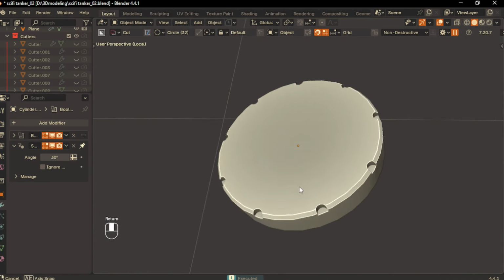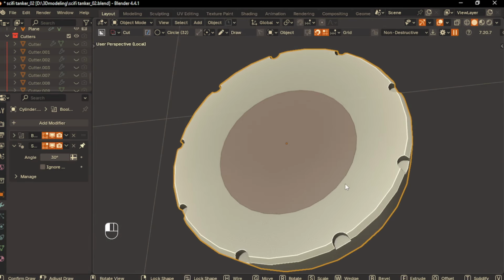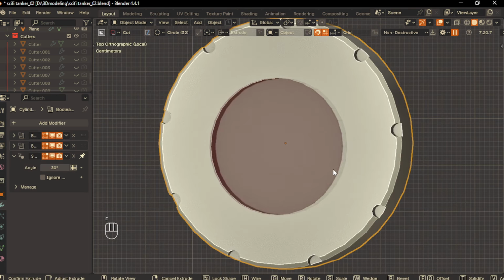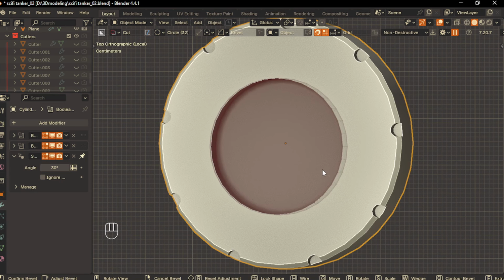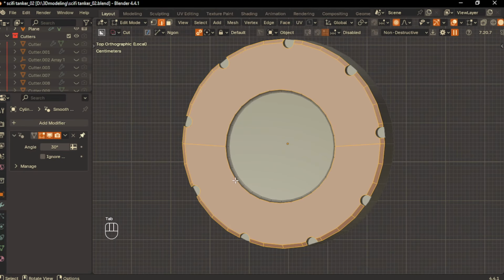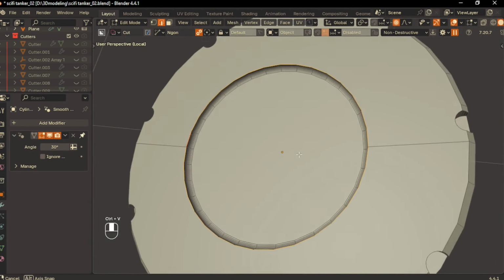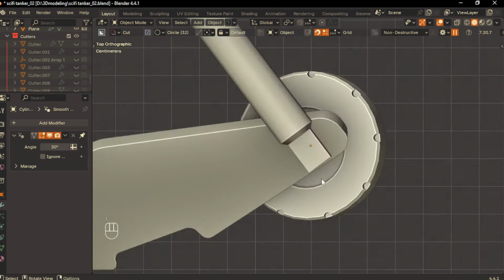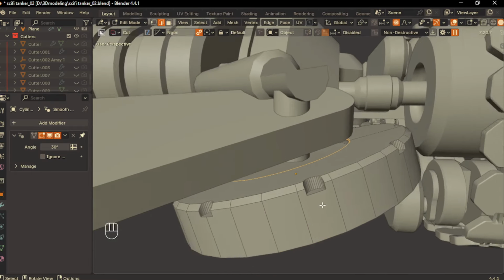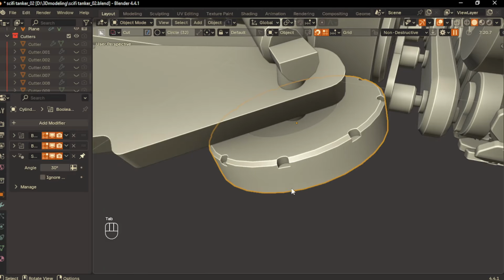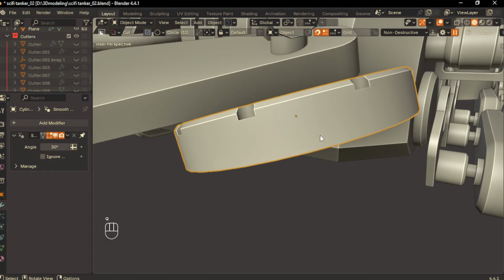Now let's make one more circle cut, this time pretty large. Place it directly at the center, push it inward and apply bevel, then cut it. Now smart apply and switch to edge mode and select these outer edges, run a chamfer to define the edges cleanly. To fix the shading issue, let's add a few more loop cuts, then smart apply again and finalize the geometry.